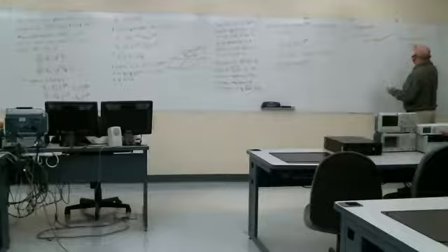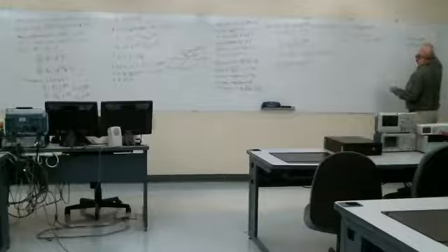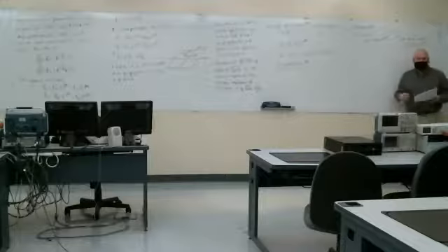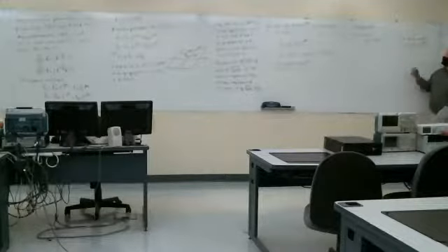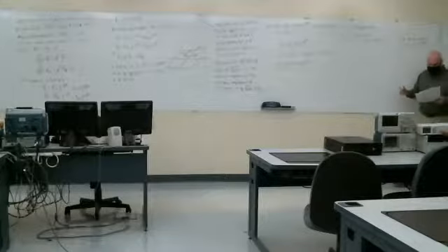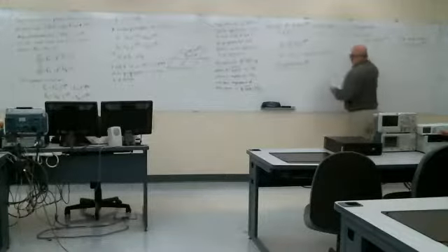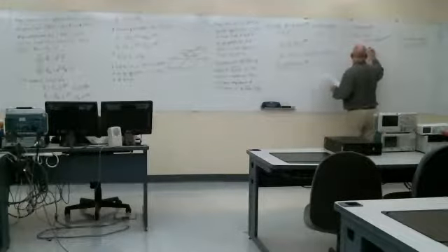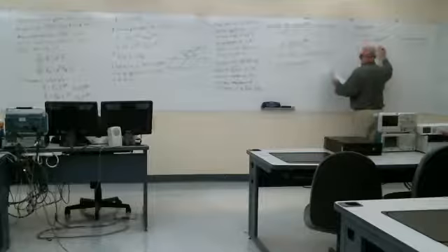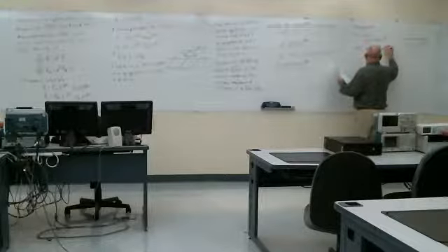E0 has a magnitude and phase, so we'll call it phase angle psi. So in general, it may be a complex number in the phasor domain. And similarly for H, E0 over eta, e to the minus j beta z.